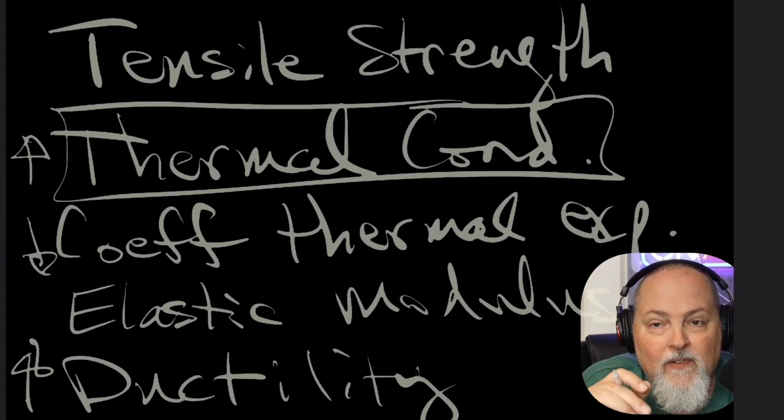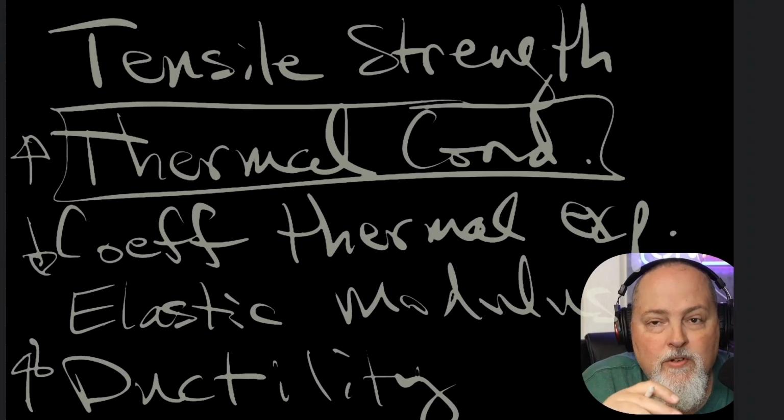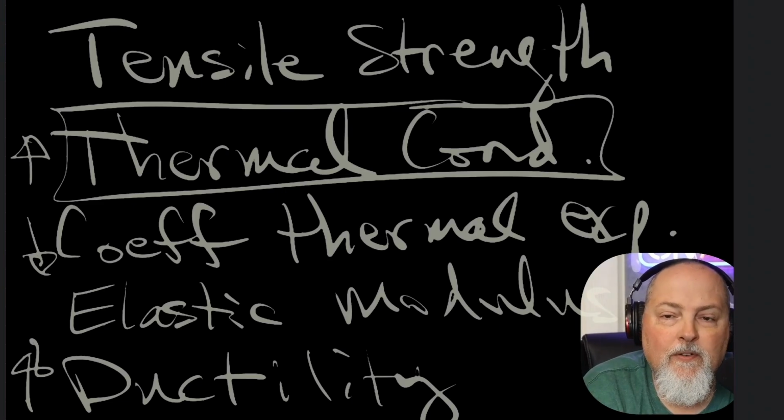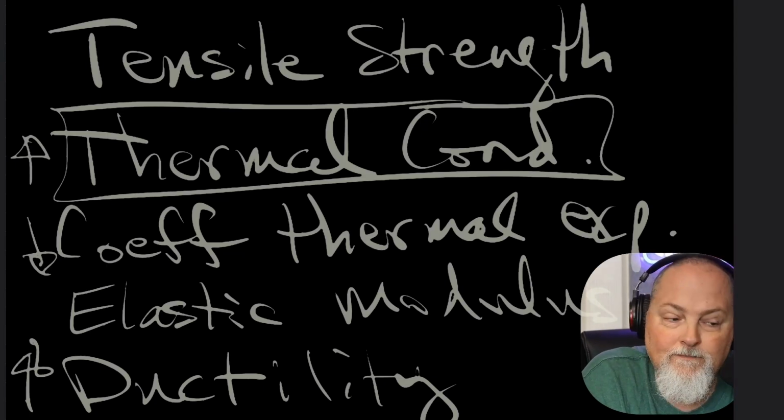Lower modulus of elasticity also helps because the material can accommodate more strain with less stress. So if a material spreads heat well, expands less, and can deform more before failure, it handles thermal shock better. That was a mouthful. All right, let's pause here for a question.